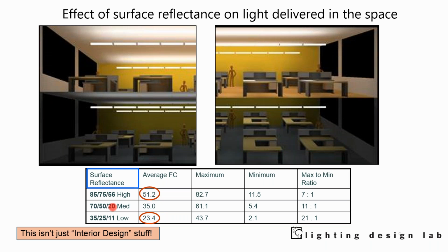Well, let's say that your customer has very aggressive energy saving goals. They want to be a LEED building, and so you're really pushing on the tolerance of what your lighting system can do. So you run your model. You haven't talked to anybody else about what the reflectances are going to be, but you just assume. So you're at 35 foot candles. That's their target light level.